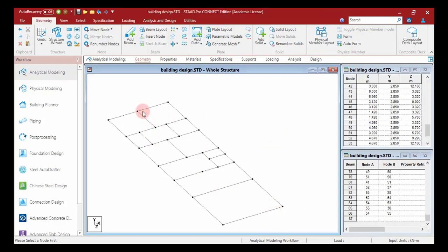So what you can see, I have created these roof beams, and please note the location of the roof beams is such that they support the wall which is going to be present at the first floor level. Based upon the plan, wherever we had the walls in the first floor level, below that I am providing these beams. Okay. So I have finished the layout of beams up to this level. Further, let me see.